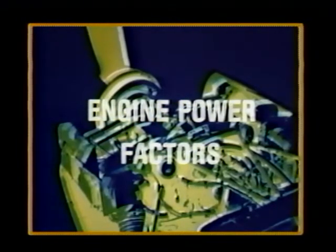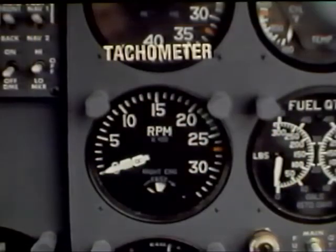Now that we know how to measure engine power and are familiar with the various efficiencies of the engine, let's look at a few more factors that affect engine power. To begin with, there are two instruments that provide an indication of how much power an engine is producing. The first instrument is the tachometer. This tells the engine speed, which is directly related to the number of power strokes per minute.